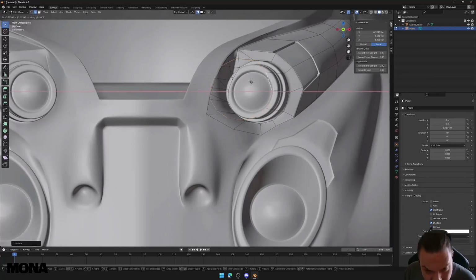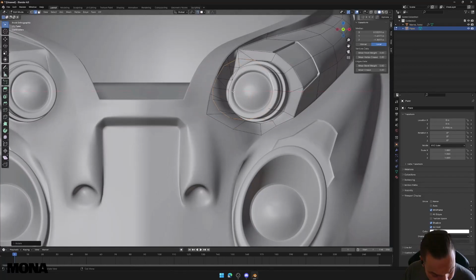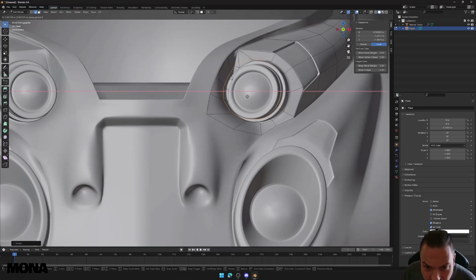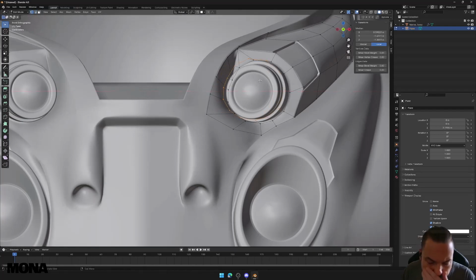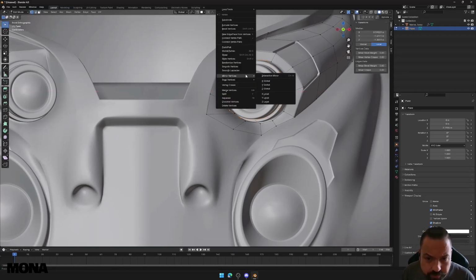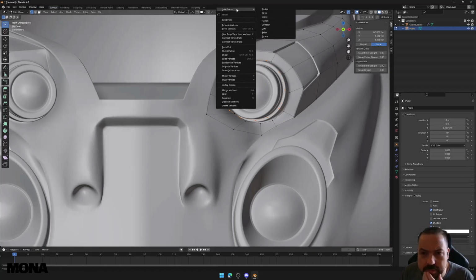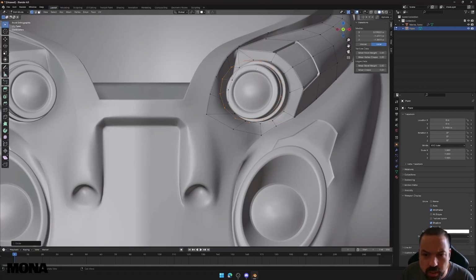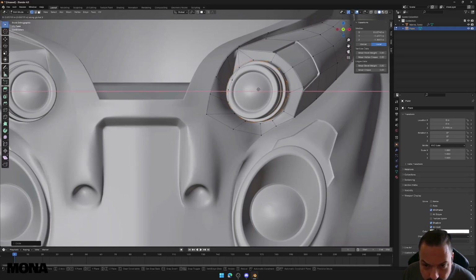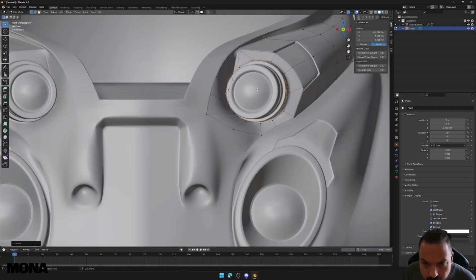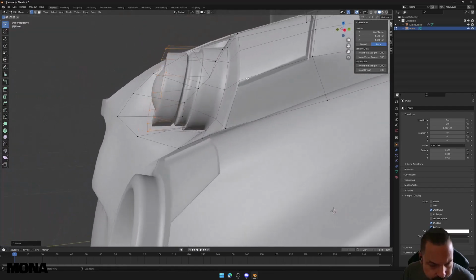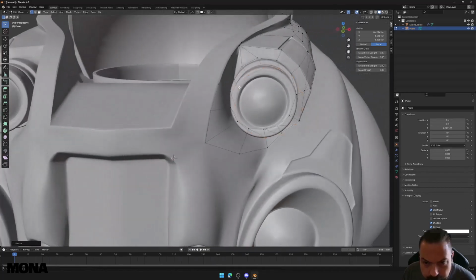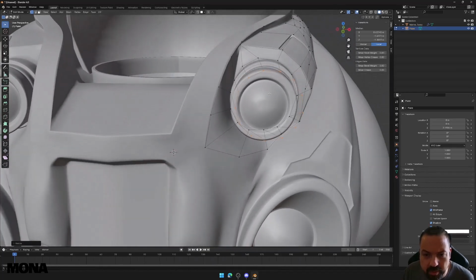Move that across a bit, so that GX, turn off snap, because I don't want it to snap at this point. Now, a very useful other add-on that is free, comes with it, is Loop Tools. So for example, if I go circle, that will make that into a circle, which is what I want for all the reasons. So let's scale that down a bit. And I can clean that up a bit.